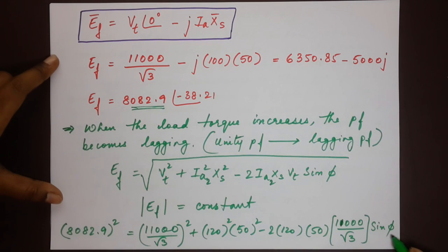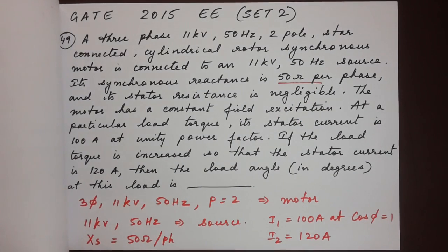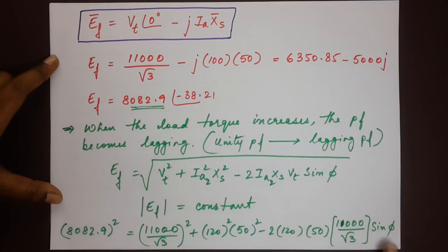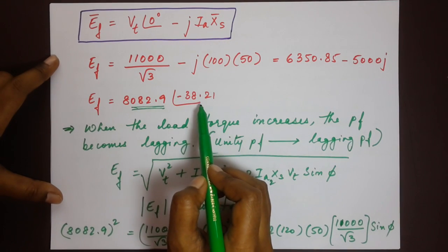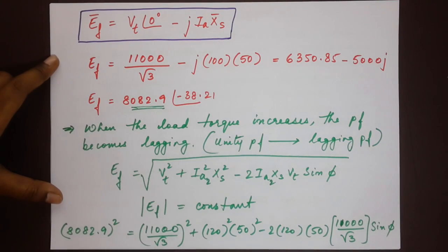We need the value of phi because we are trying to find out what here? We are trying to find out the load angle. This is not the load angle, mind you. We use this in order to find out the load angle. The load angle is the angle of the field EMF. We'll come to that. So first we solve this equation here to find out what is the value of phi. Now that very same equation, I am just going to isolate phi.